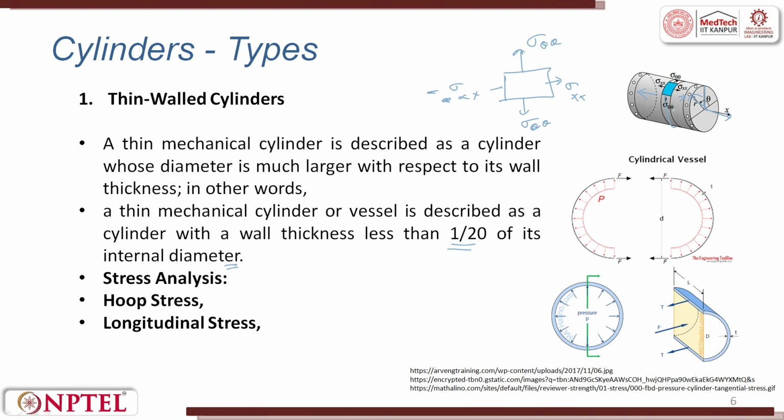So when we try to section a cylinder, we will see how the forces are coming. When the pressure is acting, d is the diameter and t is the thickness. So generally in a pressure vessel, it always happens like this. When we try to take a cross section, whatever you try to solve in this direction, this is half. When we solve this half, if you multiply it by 2, this half also comes, or you try to do it only with this half. In fact, when there is a cylinder, we always try to solve the problem for a quarter.